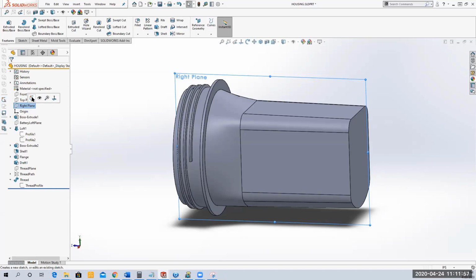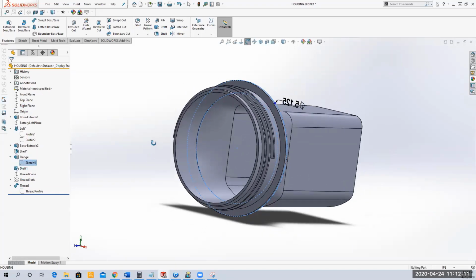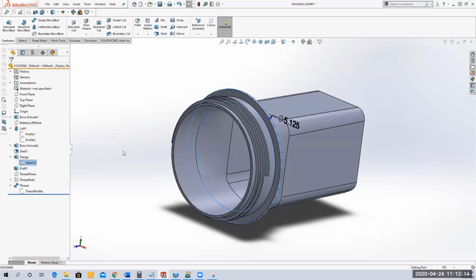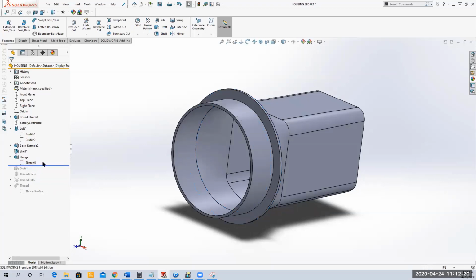Before you proceed, Elise, I've got one question. Sure. This is back when you put the flange on there. You selected the interior circle, the interior profile, and I selected mine, but it was somehow cut up into segments, and it's telling me that the sketch has more than one open contour. Is there a way that I can combine them? Because you should just have one circle. Right, I should. If you don't, I would just delete it and just draw a small circle. All right, thanks. I'll do that.